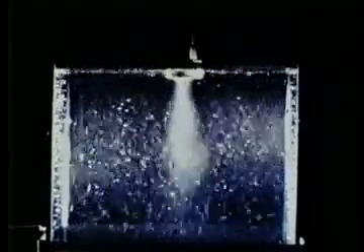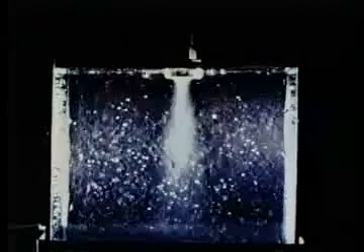The high collapse pressures and the mixing caused by ultrasonic cavitation is put to good use in industry. For example, for accelerating chemical reactions, industrial cleaning, and homogenization of milk. Let's now look more closely at the motions of the small transient bubbles which cause so much trouble. These bubbles have a life history measured in milliseconds. They grow during their passage through the low pressure region and then collapse as they enter the region of increased pressure. If the bubbles have a relatively large initial gas content, they will collapse and then rebound, as in these